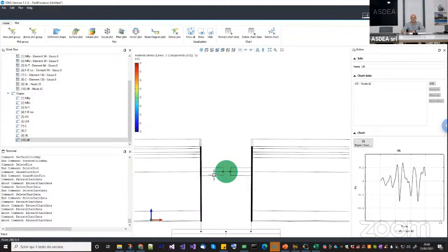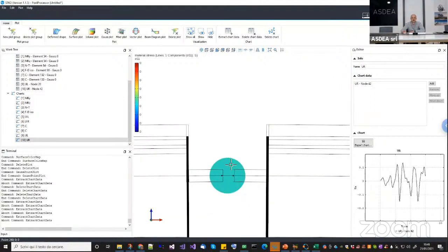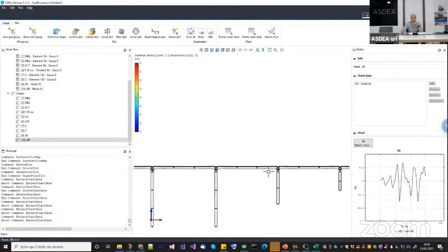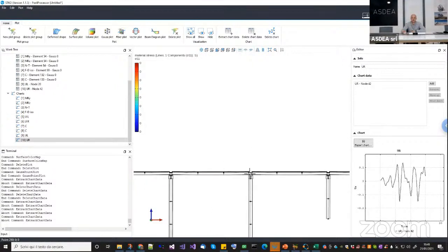And in this case, it was a simple unilateral contact. Remember that instead, in real life, friction contact is much more difficult to solve because you don't have only normal contact or unilateral contact, but that one is coupled to frictional contact through a Coulomb-like criterion. And most of the time you don't have that contact only in a few located places. Sometimes you have contact all over two huge contact surfaces, and that is very difficult to solve for the Newton-Raphson method because it is a very strong nonlinearity.